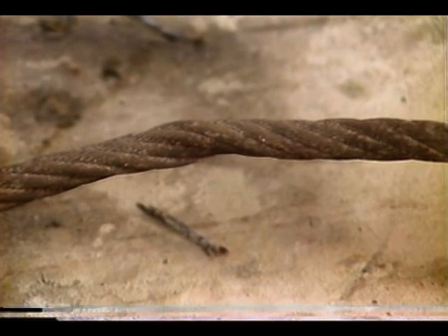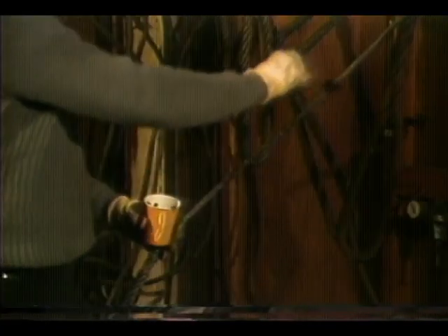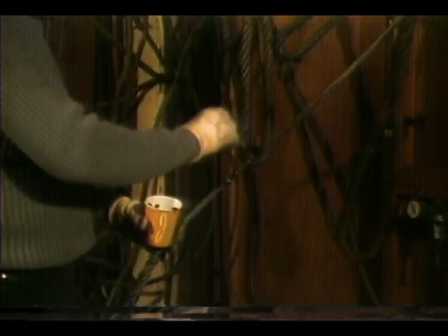Store all unused rope in a clean, dry place, preferably off the ground. Never use rope which has been cut, badly kinked, crushed, or otherwise misused. Lubrication is the prime factor in extending the working life of wire rope. Lubrication not only reduces friction between individual wires in a rope, it can also prevent internal rusting.